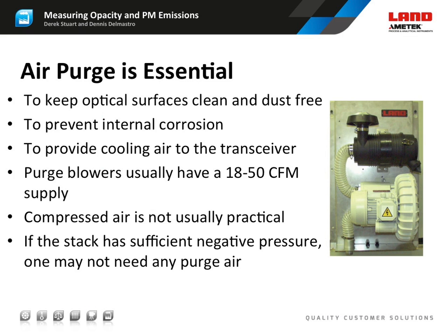One of the more important auxiliary components on any opacity monitor is the purge system. The purge system is essential for several important reasons: to provide air to keep the optical surfaces clean and dust-free, to prevent internal corrosion in the system, and to provide some cooling effects to the transceiver to enhance the life of the critical electronics. Usually purge blowers range in capacity from 18 to 50 CFM and purge both sides.